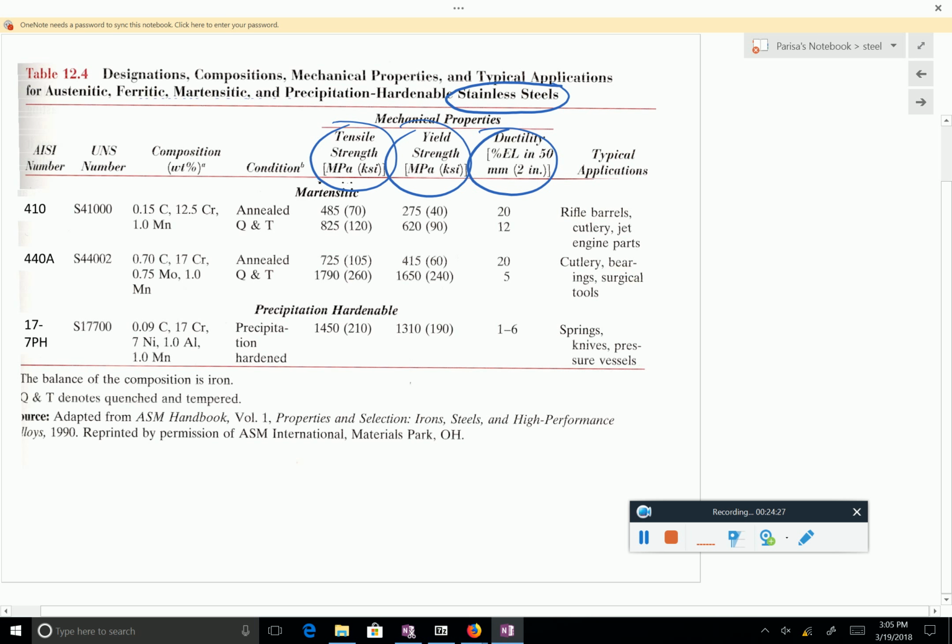So what you have is that you have codes with tables inside. Once you want to design a steel girder or a beam, you figure out what you need in terms of yield strength, in terms of tensile strength. Then you go to the code and you look out for the right material, which has the lowest cost but gives you these properties. When you take other classes, like in a steel design, you are going to learn how to do that.